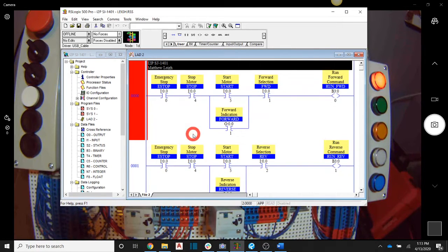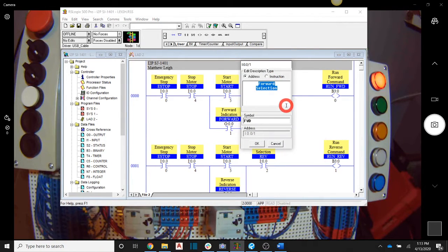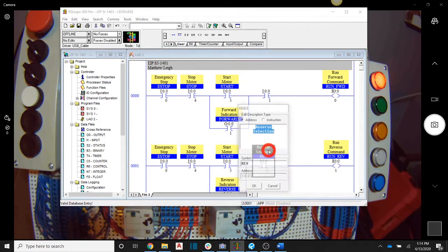All right. So the start switch is no longer going to be the start switch. It's going to be a forward switch. And so we have a symbol that we want to call forward for that. And down here, this start switch will be replaced with a reverse or the yellow push button. But we already have symbols of that same name. So we need to actually remove those from our selector switch, and we need to move them over here. And the simple way to do that is just to double click, and we're just going to physically delete those out in our little dialog box there, and we're going to delete these out here.